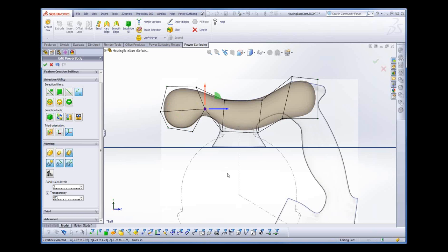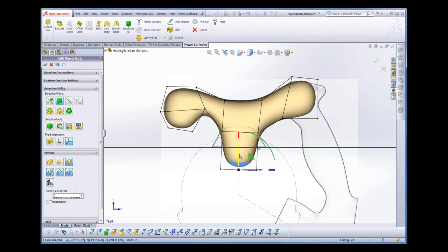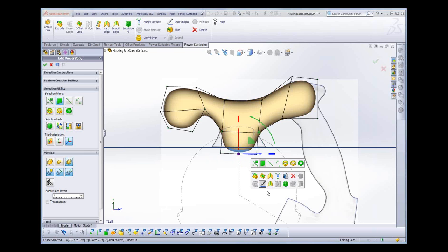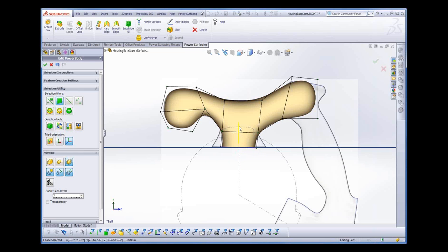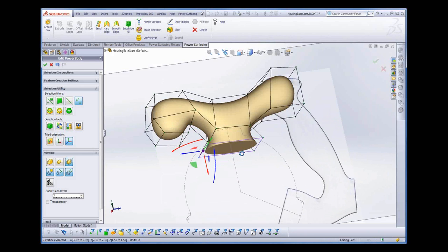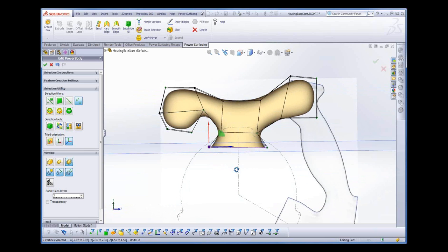Another thing we can do is select a face, and I'm going to extrude this one again. Right-click to finish the extrude. And if we give a 100% edge weight to this guy, we've now got something that we could, if we wanted to, snap to a plane. It won't have the relationship where it's parametric, but it can always be re-snapped. So once you've put a hard edge, a full 100% edge weight on something, it can be put into a position where you can get the dimensions on it.